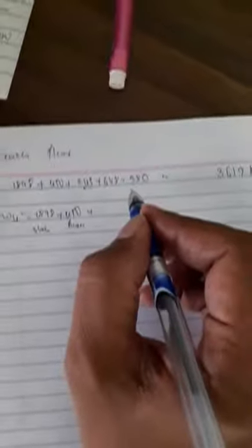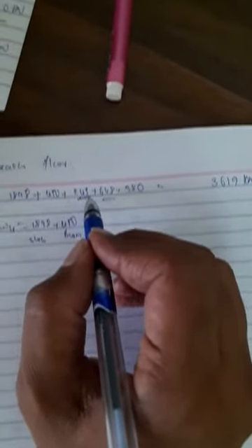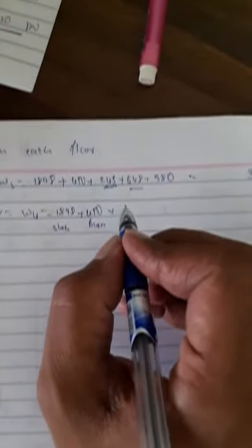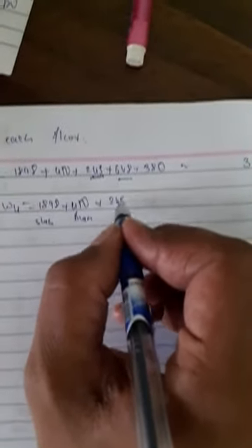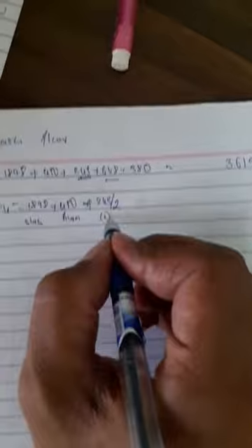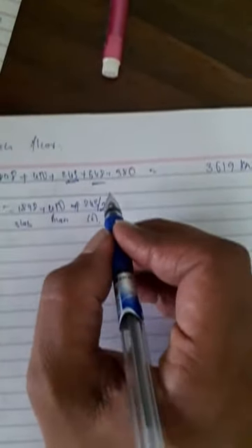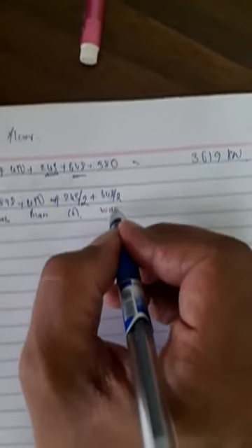Beams are included. Next, we have to include 243. And what is 243? Due to columns. What the code says is 50% of the loads you have to include on the top floor. So 243 divided by 2 for columns. Next, similarly for wall loads, 648, again you have to include half of the wall loads.